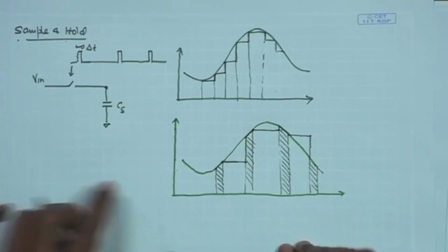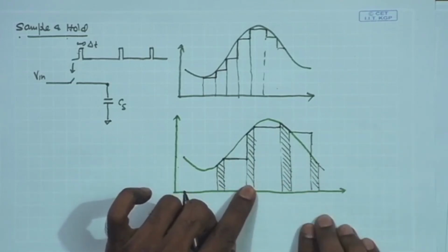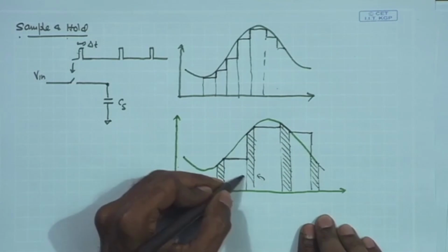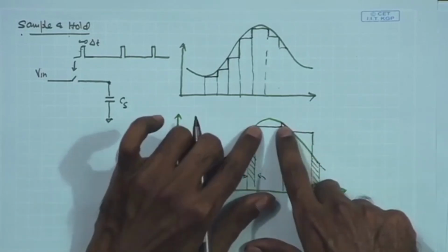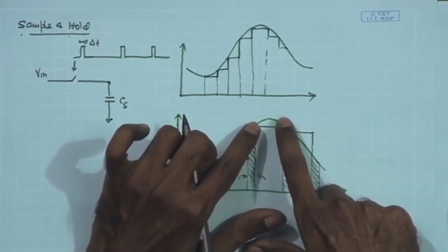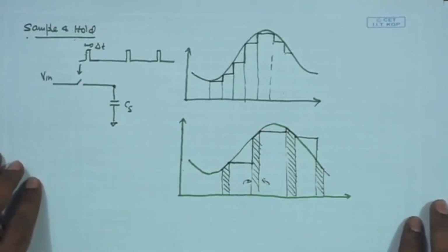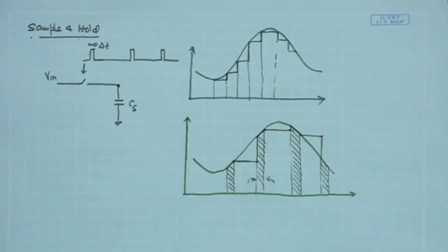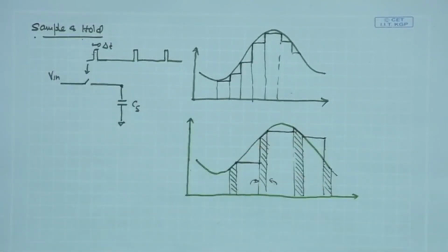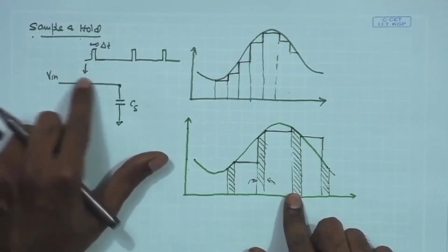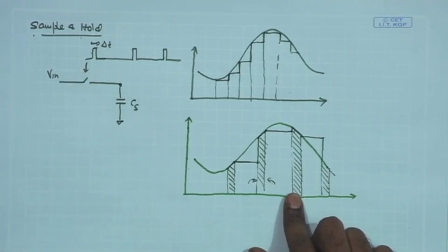Of course, if we want this entire sampling duration to be allocated to the digitization process, we would like to reduce this as much as possible. We would like to reduce the T on as much as possible, so that the A to D converter can utilize the maximum of this sampling duration in conversion of the analog signal into the digital value. So, it will be favorable to minimize it as much as possible, and also that minimization would require certain design consideration with this switch, what kind of sizing, what kind of transistor configuration we are choosing for this switch.